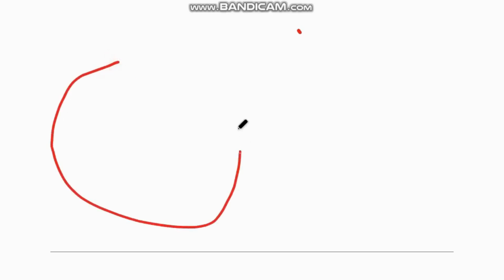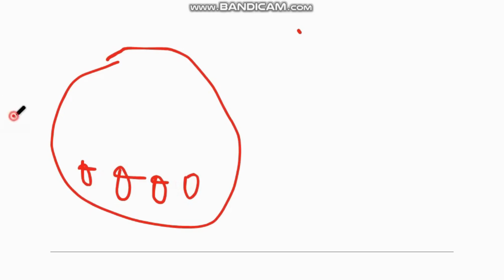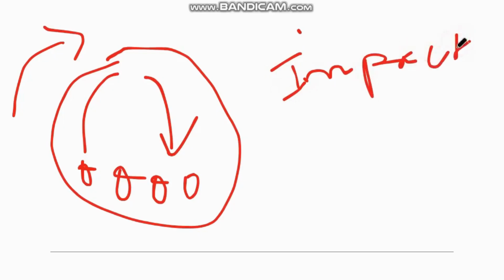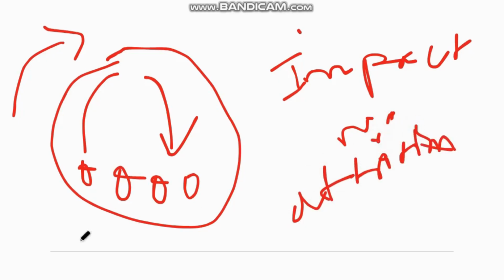And the next very important factor is the speed of the cylindrical vessel. If the cylindrical vessel containing the stainless steel balls is rotating at a high speed, then immediately these balls get lifted up and come down immediately. Only the impact will take place, there is no attrition. Then also we cannot get efficient size reduction.